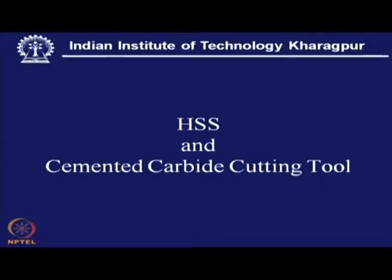Now, here we can look at the two major cutting tools we are using, though there are many more like ceramic, diamond, cermet, CBN. There are many other combinations of those hard materials by getting the nitrides, carbides, borides of all transition elements. But even after that, the major role is played, on one side by HSS and on the other side by carbide.